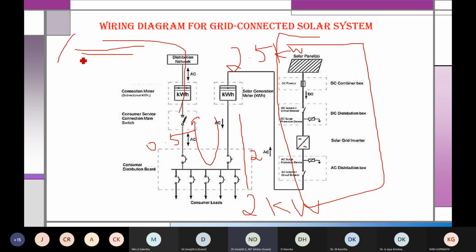They have switched off the supply from here and they are working on the transmission line, assuming that there is no supply. But this is a grid tied inverter concept. Here you can see 2.5 kilowatt is a generation, so the remaining 0.5 will be given to the grid automatically now. But the grid is off and people are working on the lines. So this will create a lot of safety issues.